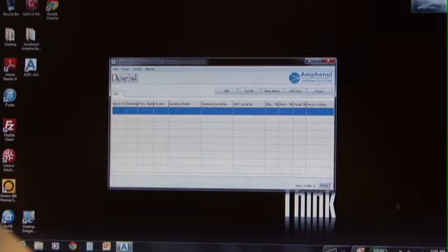Device scan. The scan function will interrogate the AISG bus and display all AISG devices found. RET device types will display on the RET panel. TMA devices will display on the TMA panel.